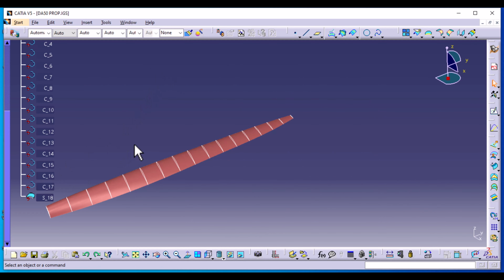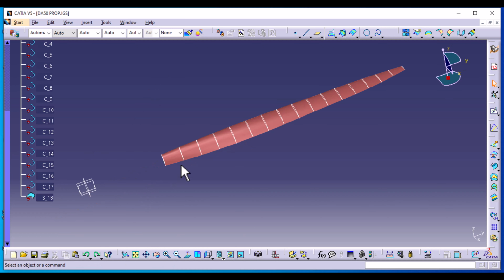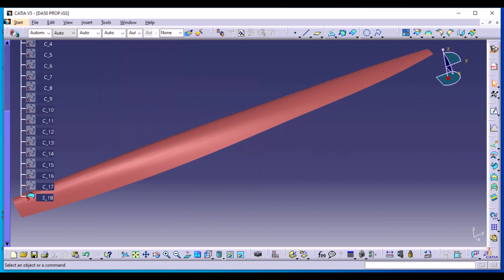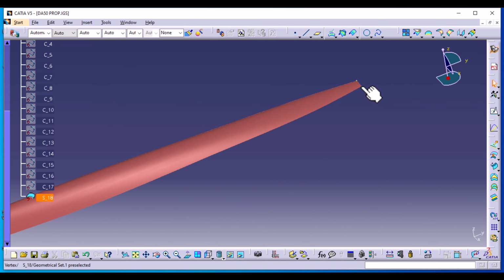And remember, the generated loft is not like completely touching all these curves. So you're going to hide these curves, and you can now create a boundary of the actual geometry, okay?